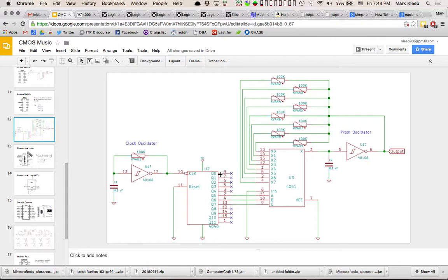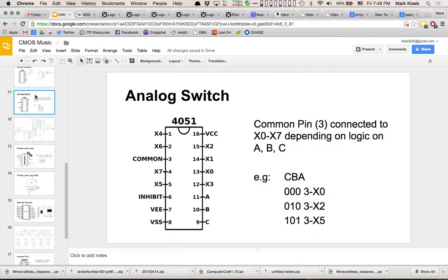They do this so when you're connecting them together, it's very clearly labeled what each pin is. Even the 555 timer doesn't look like how the chip layout actually is. That's why I go back and forth between the data sheet and the diagram, because you want to know where that pin is when you're prototyping versus in Eagle.